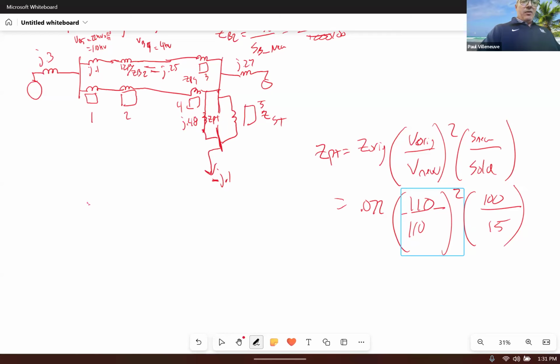So in my transformer, I have my incoming power over here, and I have 2 completely separate windings. So it's not a Y connection. It literally is 3 wires coming in and then 6 wires going out. So there is no Y. I mean, this winding could be a Y here, or it could be a delta. It really just depends on how the transformer is configured.